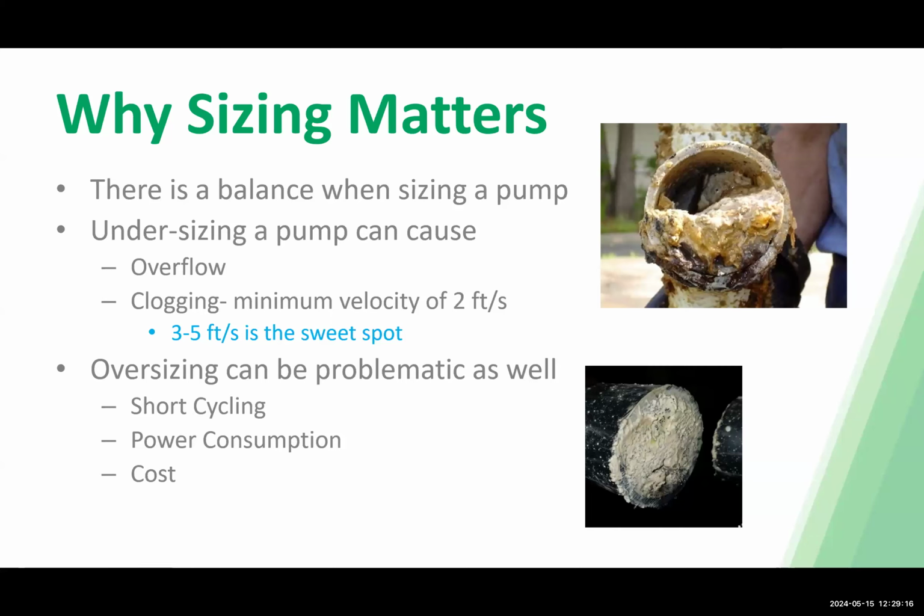Going back to that 3 to 5 feet per second, typically the 8 feet per second is usually the maximum that we recommend in really any kind of application, mainly because water is naturally erosive. So if you're going above 8 feet per second, you're increasing the possibility of the water eroding your valves and fittings and causing premature failure from that end.